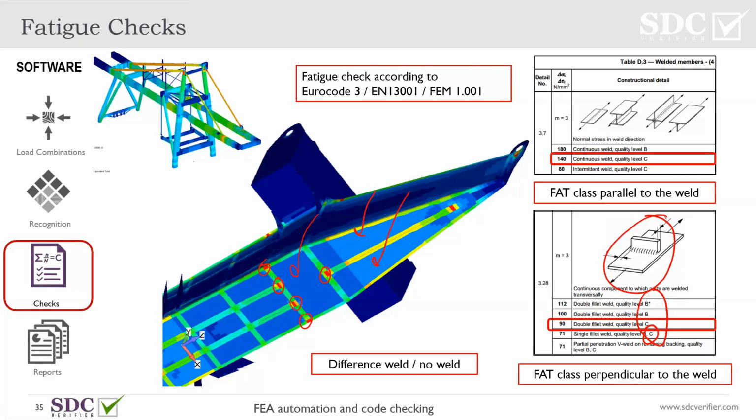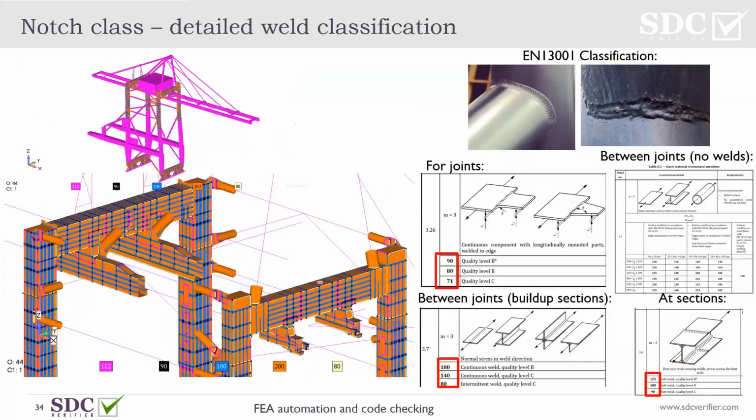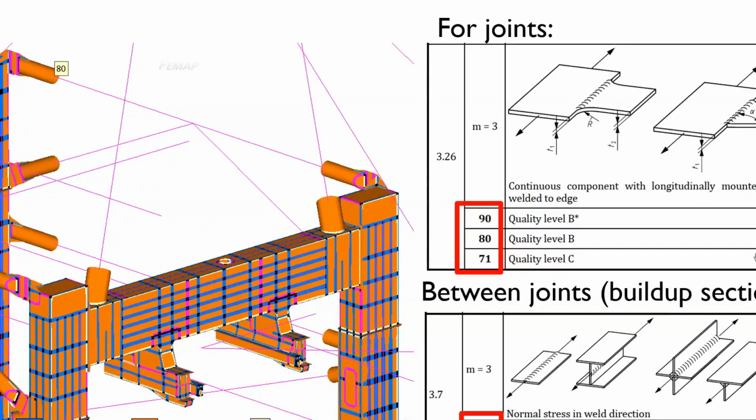First of all, about conservativity. EN 13001 is based on the nominal stress approach. It is directly mentioned in the standard. So if you have a very detailed finite element approach applied, for example, when you have modeling with shells and so on, some of your results may be conservative. It is directly mentioned in EN. It is mostly caused by the stress concentrations in our model.